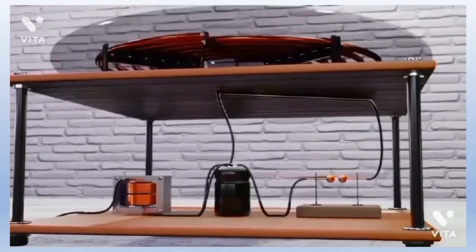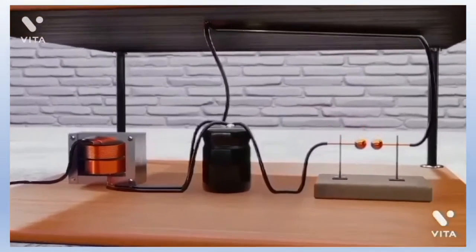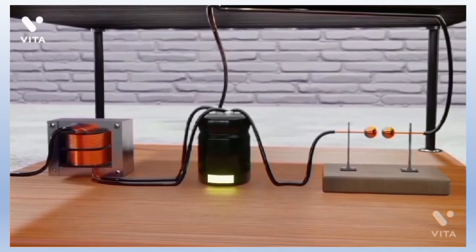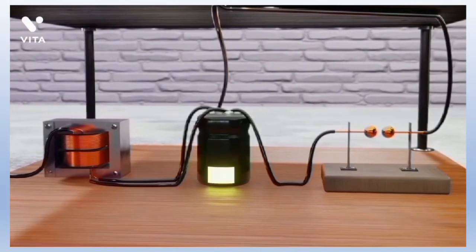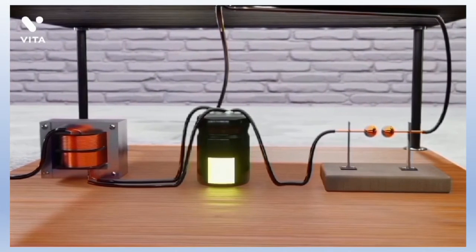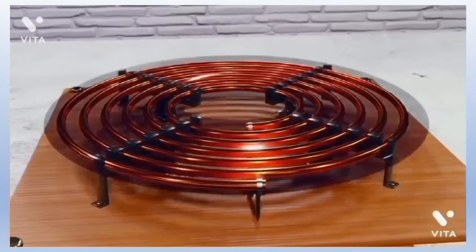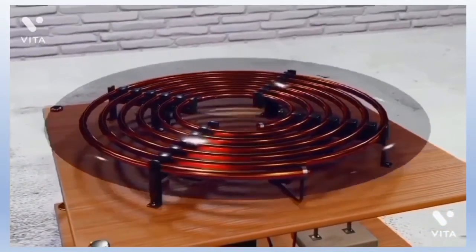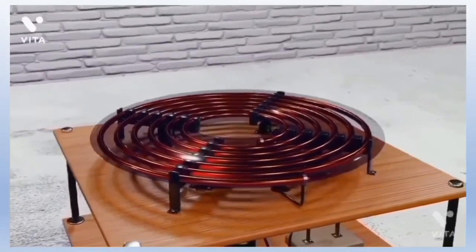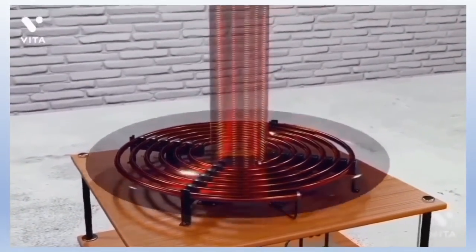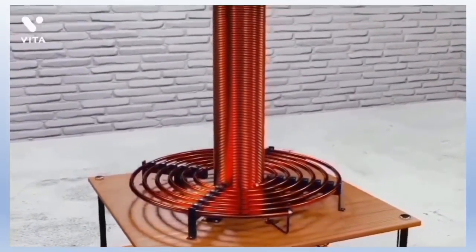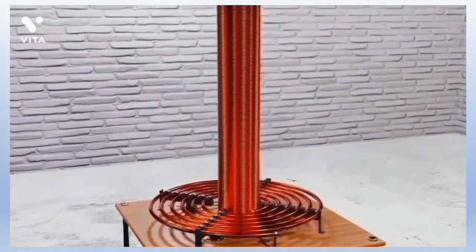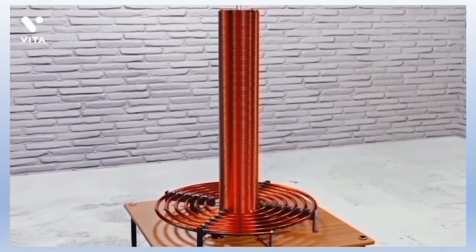When the transformer induces a current, charges begin to accumulate in the capacitor without having any other possible way. But as the source voltage grows with each oscillation, the electrons try to find another path, producing an electromagnetic field oscillating at this same frequency, which we can take advantage of with the secondary coil. Again, we will have two coils nearby, and with a big difference between the number of turns of each, which means that we will have a second transformer in our Tesla coil.